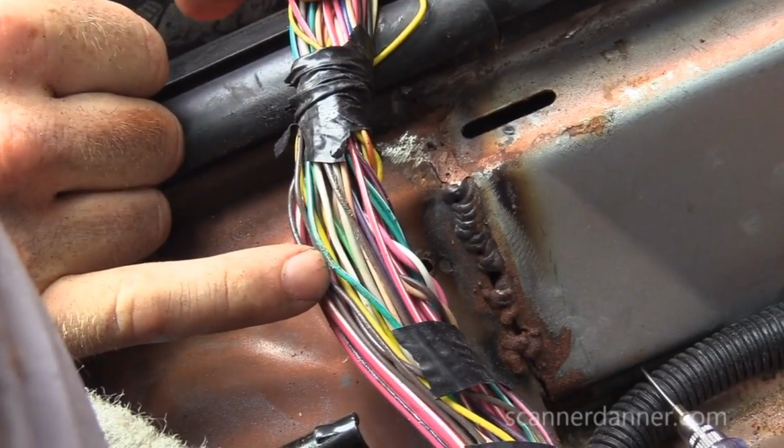Oh, that's right. I opened the door and it went clunk. And I'm like, that's not right. This car was in an accident, and then we did some further homework. That's right inside the door. When you step in the door, that's the floorboard area. Somebody did some welding, and it went through the harness and shorted that wire right there to ground. That was how we found our short to ground. So it's a great video to watch in locating shorts to ground that are intermittent, side note, but this is a bias voltage lesson. There's my short, that's why the fuse blew.